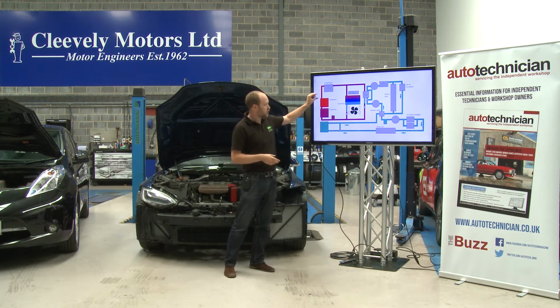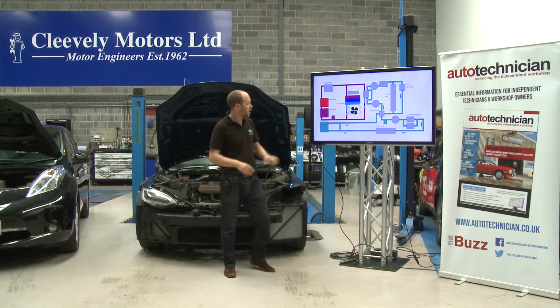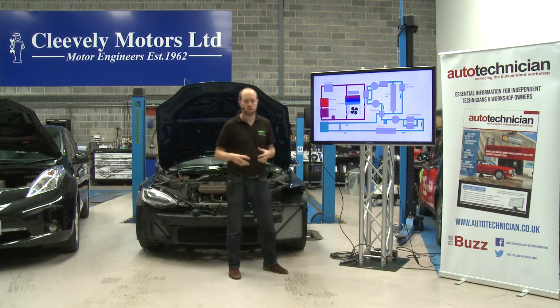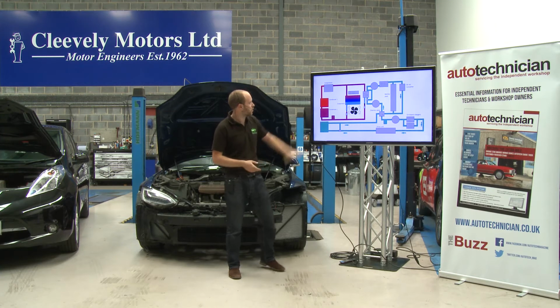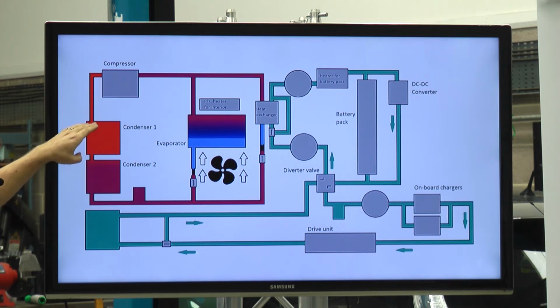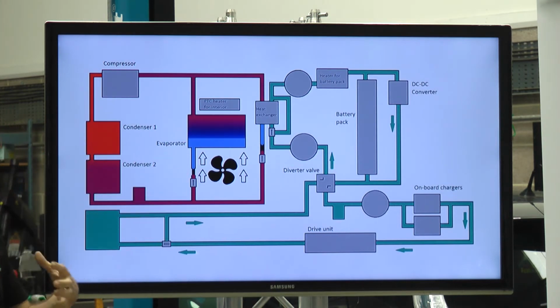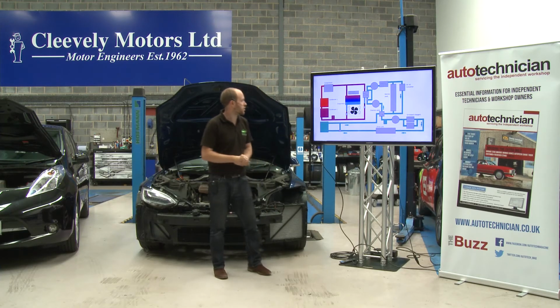So increase the pressure and it increases the temperature, which is why your compressor in the workshop is hot. And when we reduce the pressure, that's where we reduce the temperature, which is why your air tools and aerosols are normally cold because the pressure's reducing. And the basic principle of air conditioning is that we can increase the pressure and therefore the temperature on this side. We can take the temperature out of it with the condenser, and then when we reduce the pressure again, we can end up with it colder than it was before, and that's the basic principle. So that's common for all air conditioning systems.